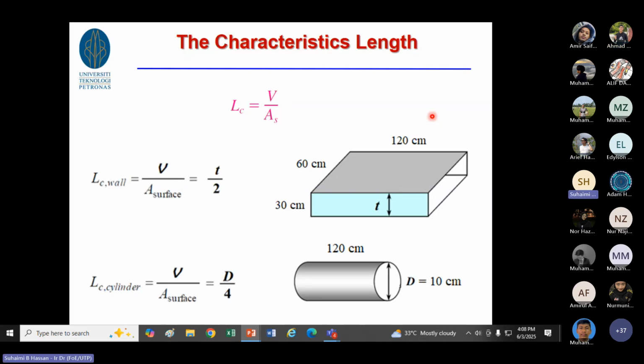216,000, right? That is one centimeter cubed, yes? Okay. The surface area, actually, don't misunderstand. For the lumped system analysis of a rectangular object, the flow of the heat is perpendicular to the surface. So in this case the surface area is only 60 times 120 times 2.